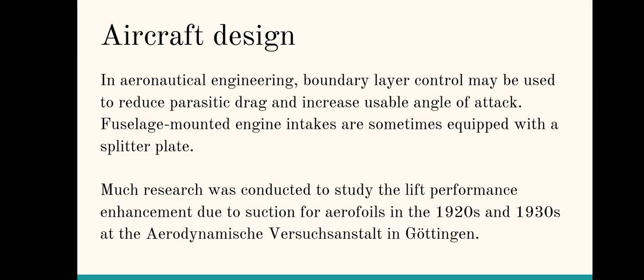At last, aircraft design. In aeronautical engineering, boundary layer control may be used to reduce parasitic drag and increase usable angle of attack. Fuselage mounted engine intakes are sometimes equipped with a splitter plate. Much research was conducted to study the lift performance enhancement due to suction for aerofoils in the 1920s and 1930s at the Aerodynamic Institute in Göttingen.